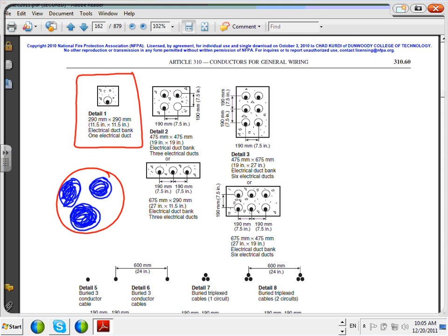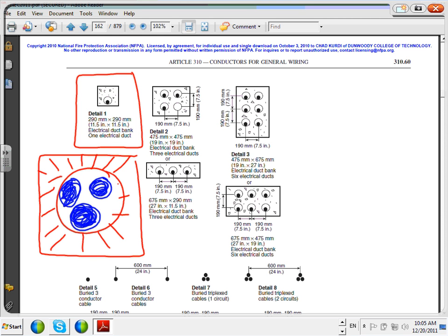That's it. And what I'm going to do with this, I'm going to put it concrete encased. I put concrete around this duct. Each one of these 3, in my case, was 4/0 MV-90. Each one of them fully shielded medium voltage, in 1 duct, encased in concrete.